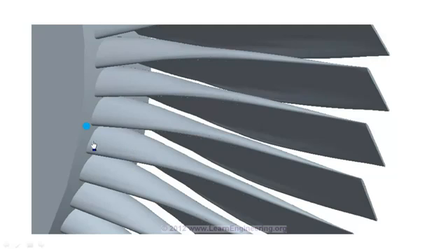When high-energy steam at inlet, the steam with high pressure and temperature, flows over such a blade, it will induce a pressure above and below the blade. And thanks to the special shape of the blade, the pressure above will always be less than the pressure below. So, there will be a resultant net force acting in the upward direction. This force will make the blade rotate, in this manner. As the blade rotates, it obviously absorbs some energy from the fluid, so the fluid at exit will have less energy compared to inlet. In the coming session we will see how we can predict the energy transfer in the fluid.